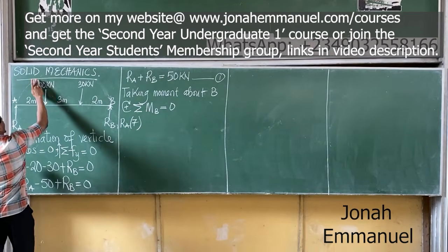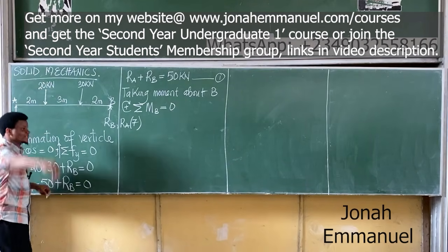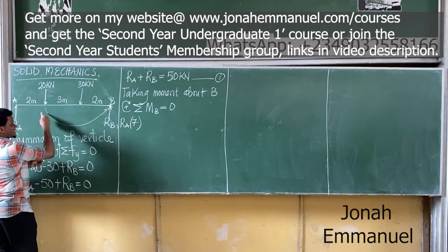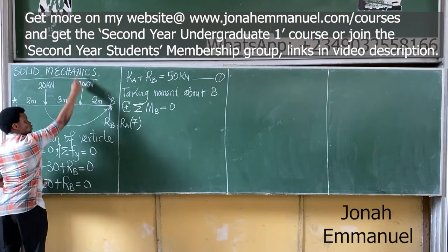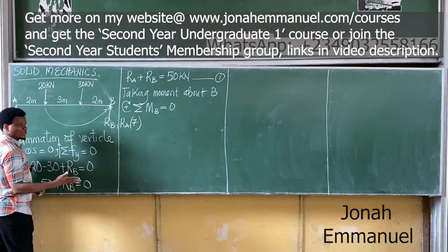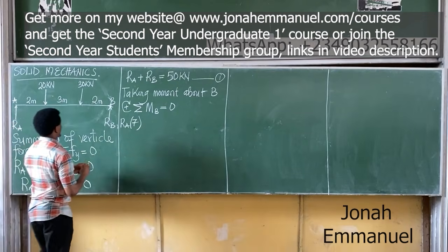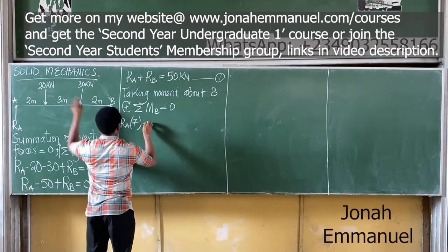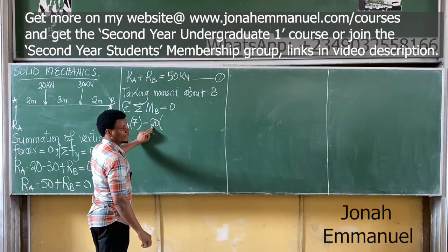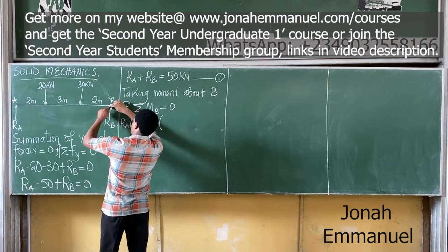This one goes off. Let's go with 20. This force is coming down, so I'm chasing it down this way. My movement is like this. What you have here, clockwise or anti-clockwise? It is anti-clockwise. So it becomes what there? Negative. It becomes minus 20. Distance from 20 to RB, what do you have? 5. From here to this point becomes 3 plus 2, that's 5.